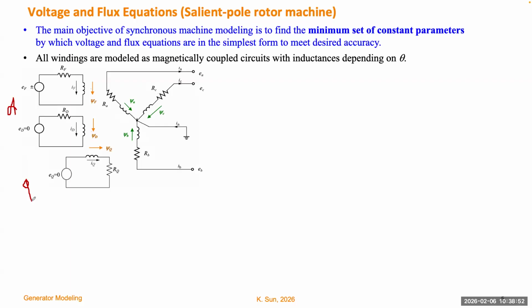Those 3 are not connected, right? They're just individual circuits. And on the stator side, we have 3 windings, but they are physically connected at the neutral point and to the ground. This is just to flow the short circuit current if you have any imbalance or any short circuit on any line of the system. Those 3 stator windings will go to the power system, right? They will send energy to the three-phase power system, so they will be connected to the rest of the system, the load.